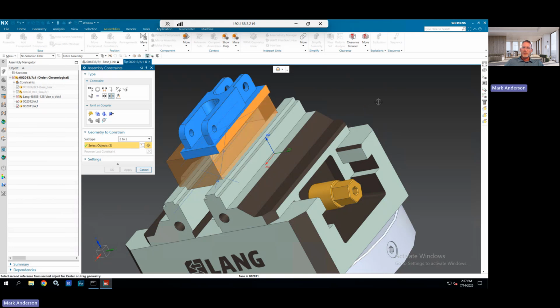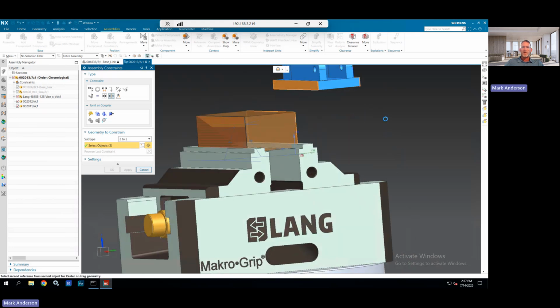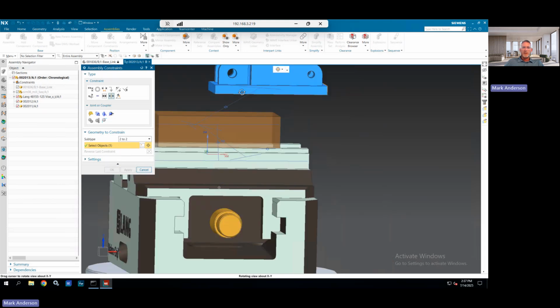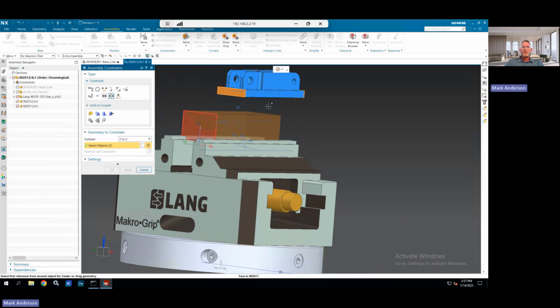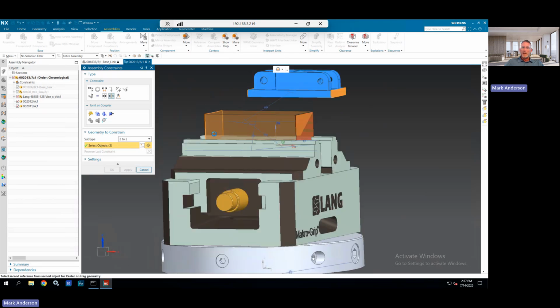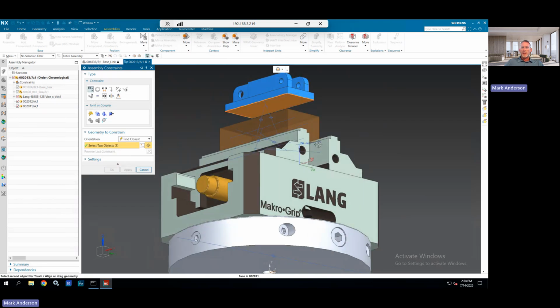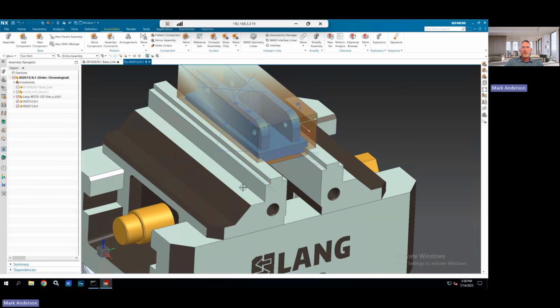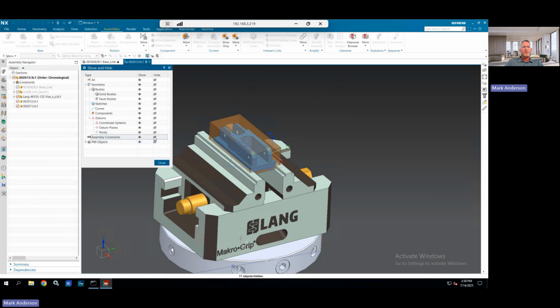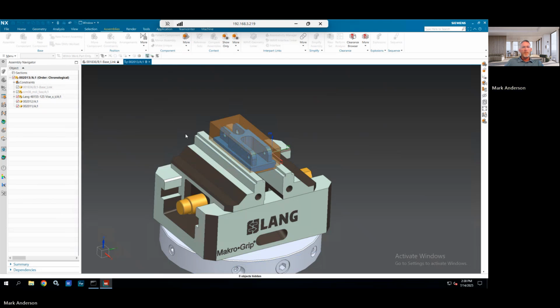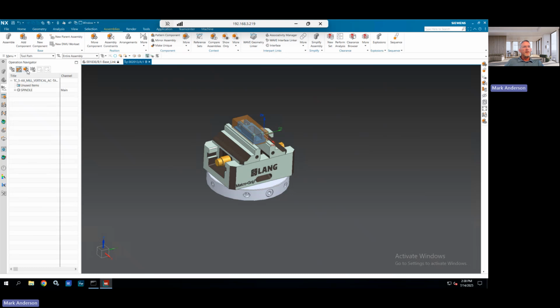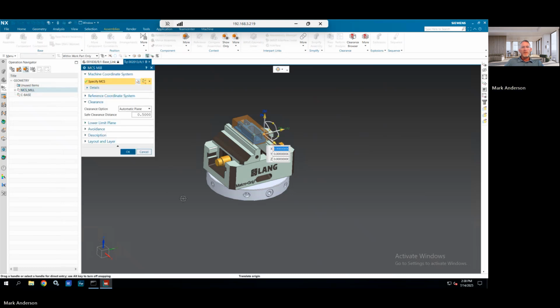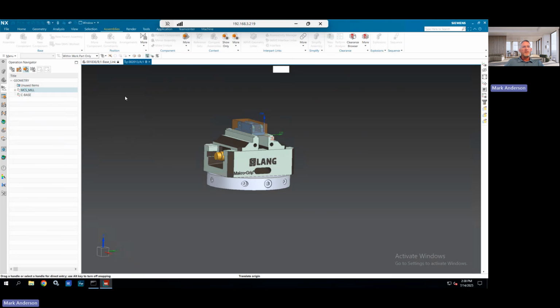you're going to notice that I'm going to just take adaptive milling and I'm going to let the software go at it. I'm not going to tell it that it has to stop at any specific cut levels. All I'm going to do, and as a matter of fact, I'm going to try to use feature-based manufacturing to allow it to do all that it needs. So that's going to showcase all of the different things and the automation that can be done within NX when you use all the different modules to their fullest capabilities. So now if I go in here to manufacturing, I'll set my work 0, center of rotation down here.